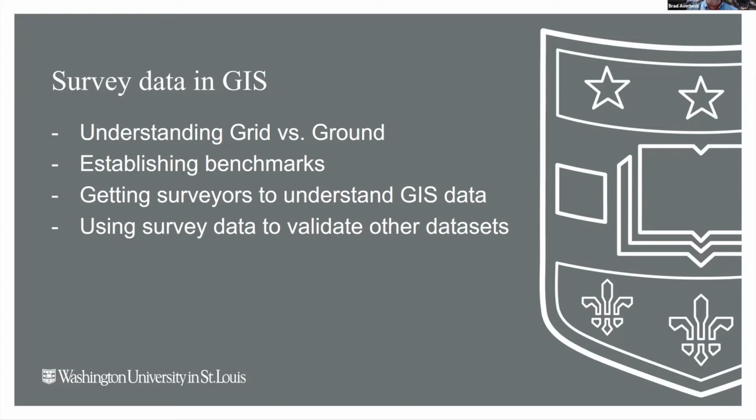But one of the things we had an issue with is when we would hand out this data to a contractor, an architect, engineer, whoever it was, they assumed that it was in ground coordinates and not grid, even though the document said that it was in grid. And so I had to have several conversations with them about, you just need to do the calculation, right? Because they thought all of our data was off and it was bad data, when it really wasn't bad data. It was just a miscommunication and a misunderstanding of how the data was stored.